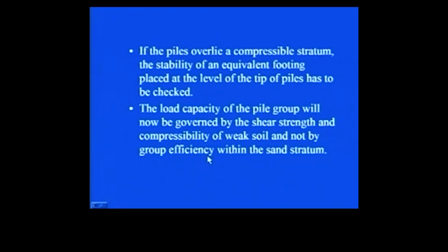That eta can be good, it can be close to unity or even more than that. However, in spite of that fact, the pile group can fail, it may not be stable due to the presence of this overlying compressible stratum.